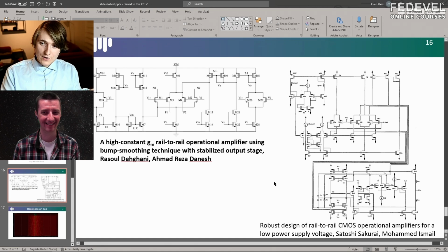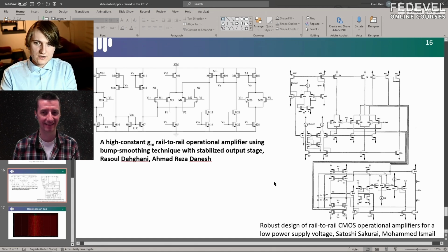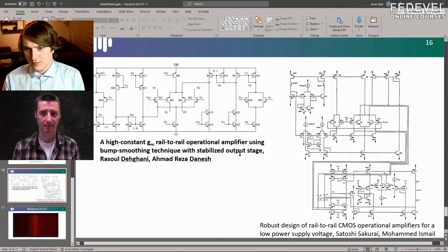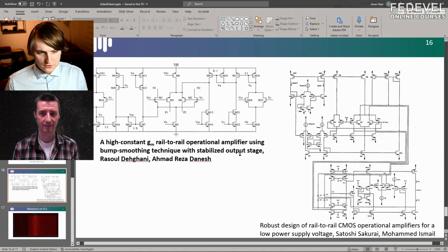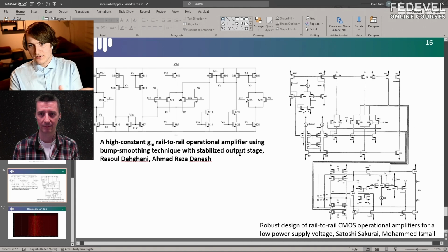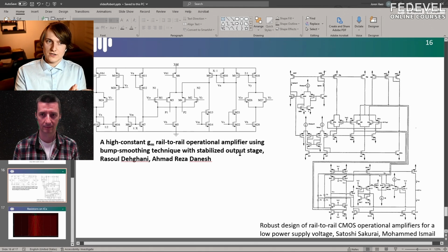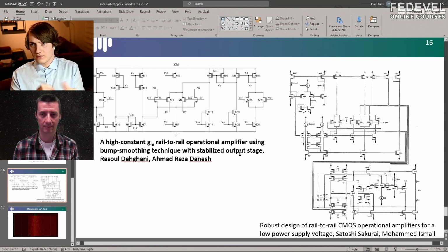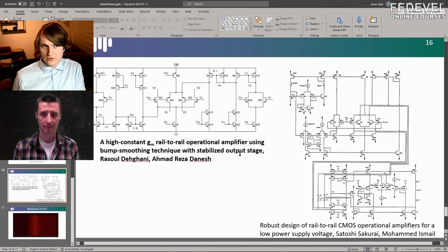And what you can then even do is, if you know how the resistor changes versus temperature, so you have a resistor that has to be 100 ohm over all temperature ranges, right? And so you have two options as a designer. Either you buy, or you build, a very expensive resistor that is completely flat over temperature. Or you take a resistor that might not be flat over temperature, but you know how it changes over temperature, and then you add on your chip a temperature sensor, and a bit of digital circuitry that can then, from the temperature, understand how it has to enable or disable certain parts of the resistor to make it larger or smaller to compensate for the temperature. And by doing that, you can, with much smaller area, with much cheaper devices, get a better performing resistor.